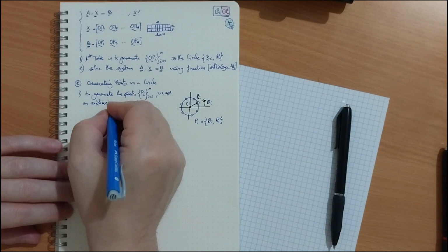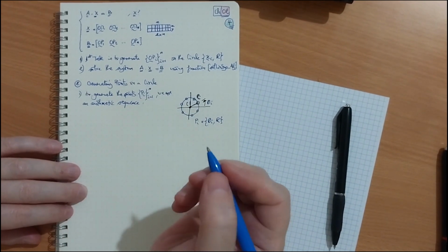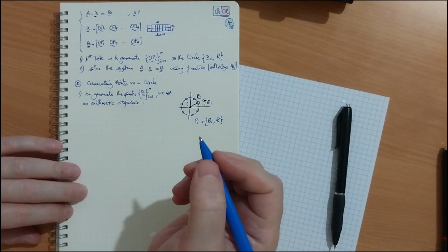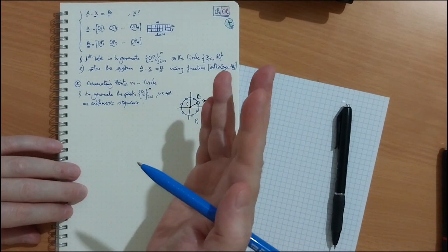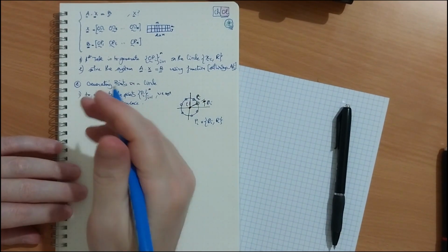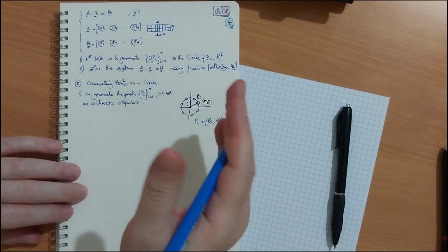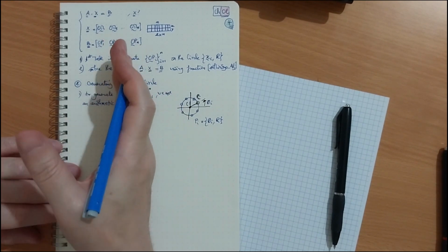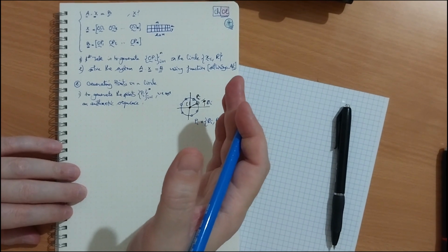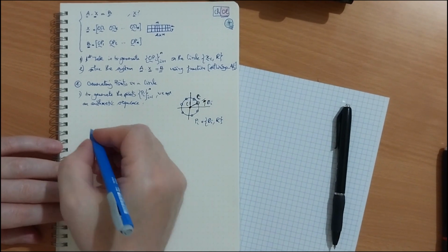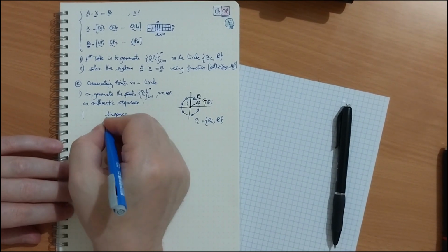An arithmetic sequence. We have seen in the practicals on MATLAB, we have done 7 practicals. The 2 first are on matrices, and you can check them if you have forgotten. We can use linspace to generate an arithmetic sequence. We know the beginning and the end. We don't have to give the step, we give the number of elements in the sequence. So we use a built-in function, linspace.